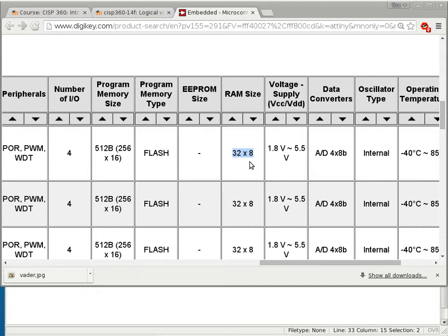No, I mean like when you use it too much and then it starts to overlap, it starts to become out of whack. But with an electronic device, it doesn't get out of whack. It uses what we call a... what is the name of that thing? Strain gauge. That's it. It uses a strain gauge, which measures how much something is bent in order to measure the torque. So it never strips because it's a non-moving part.